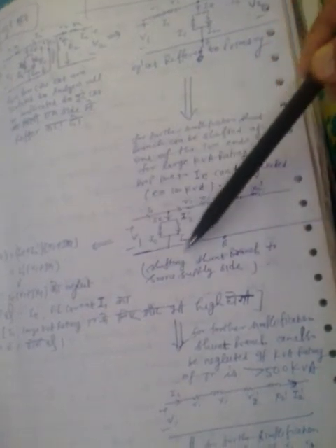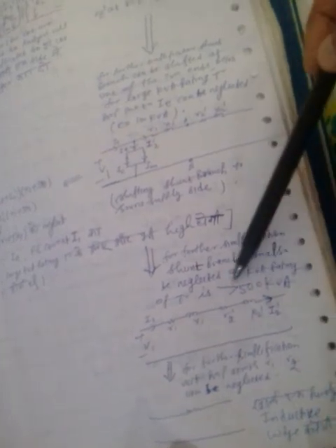The whole shunt branch, including XM and RC, you can neglect for large rating transformers. For a transformer having a rating of 500 kVA or more, you can neglect the shunt branch without any appreciable change in efficiency, right?